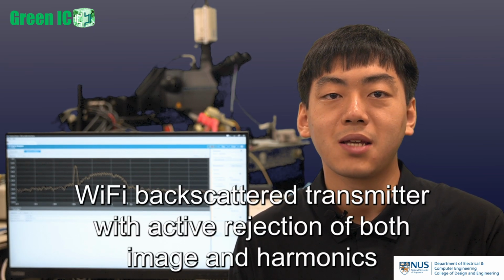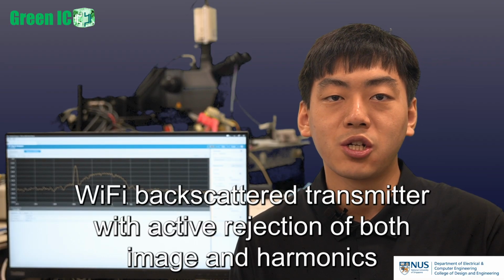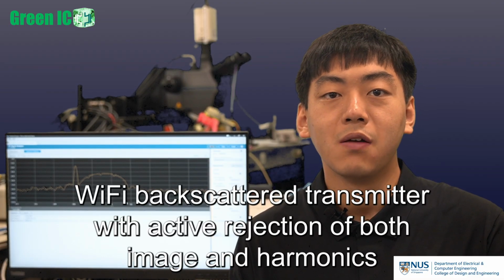Thus, in this work, we propose a Wi-Fi backscatter transmitter with active rejection of both image and harmonics via complex filtering based on reflection coefficient modulation, while avoiding power-hungry intermediate frequency overclocking. In the proposed architecture, the conventional power-hungry complex filter is greatly simplified through two key ideas.